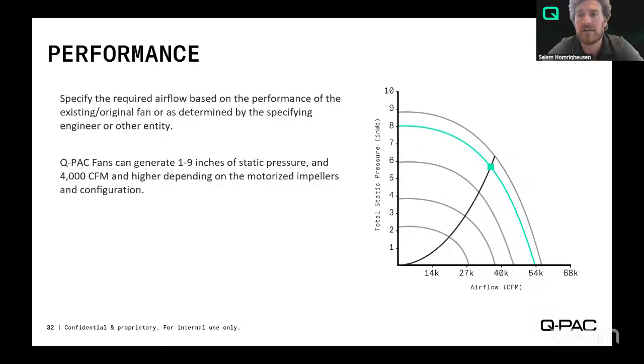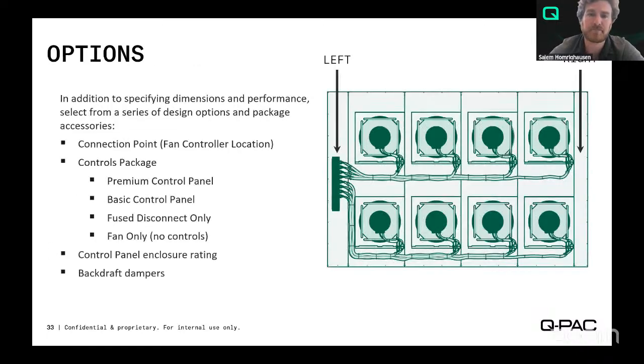So you really want to identify what your maximum and minimum performances are for that system. This is a variable air volume fan, right? So don't just select a single performance point. Look at a couple of different points. If you have access to our internal program, Quips, which you can also request access to, then you can actually see multiple options for that. And I'm just encouraging people to be thoughtful when they're making their fan selections.